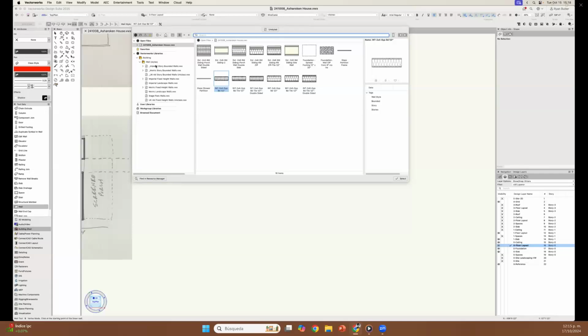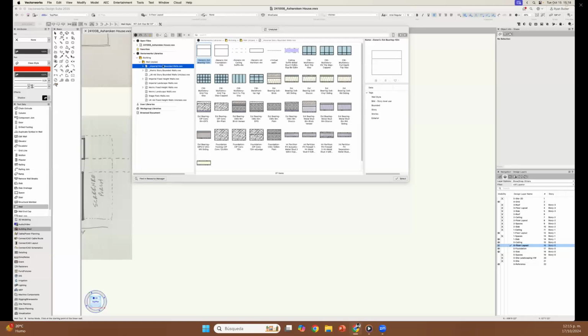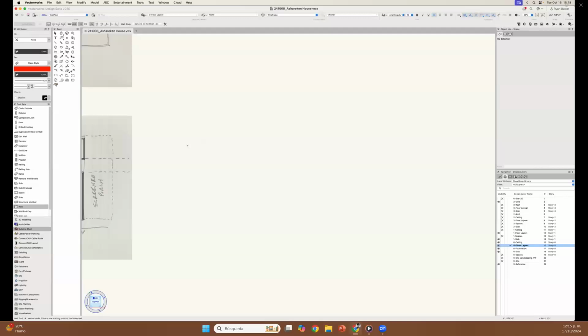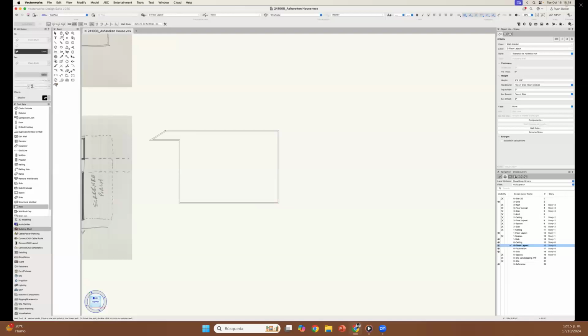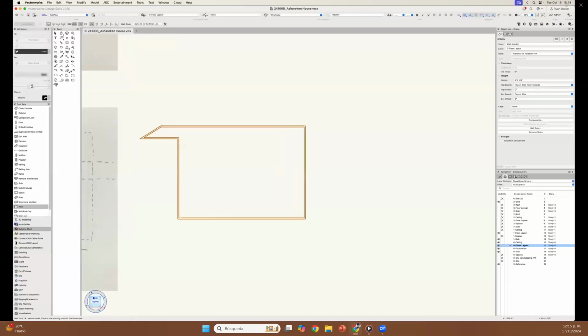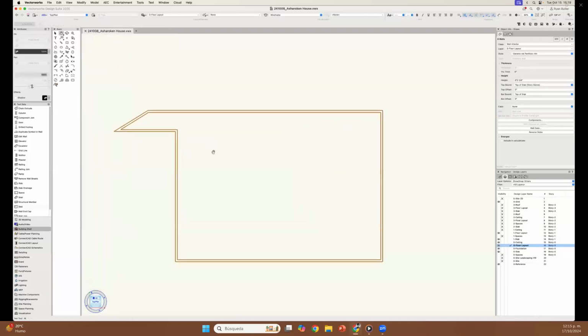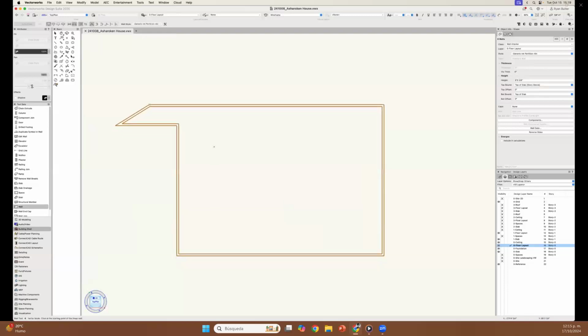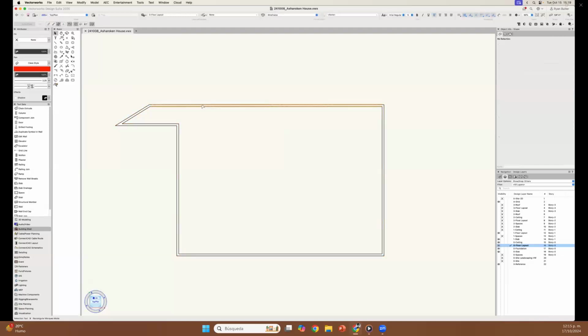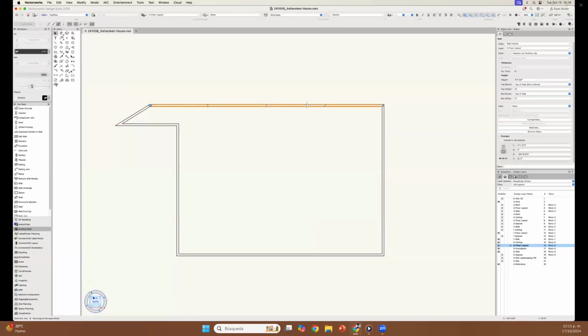So let's go to a basic generic wall when we first start out here. I have a generic partition wall here. It says 4 inches wide, that's fine. After I click that, I can just draw, click and drag, and click and drag, and so on. This is not what I want the walls to look like, but we can change that later on. Notice that the wall is all connected together, and that's what it looks like in plan.